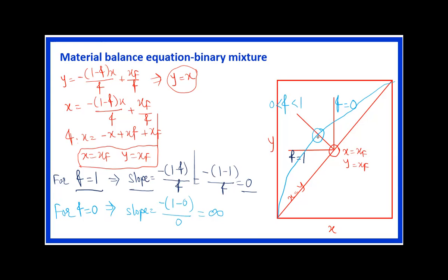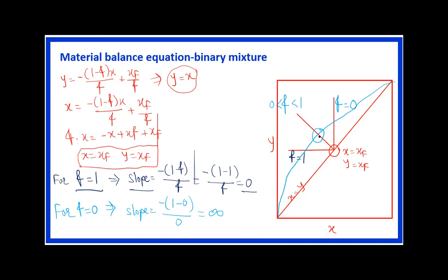So we can easily identify this from this point of intersection. So this is the value and this is another value. So it may be indicated as x1 and y1. So we have to identify the condition, then we have to calculate the slope, then we have to calculate the angle for the operating line, and then where it is intersected with the XY diagram, that point indicates the x1, y1 values, that is nothing but the mole fractions or the compositions for that particular condition.